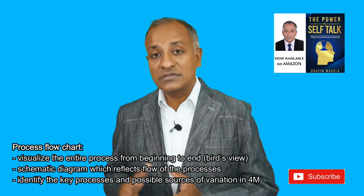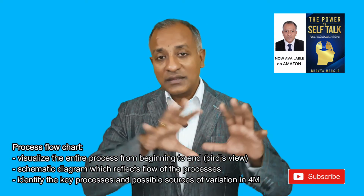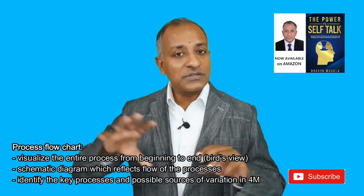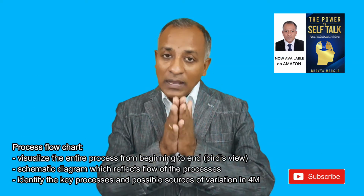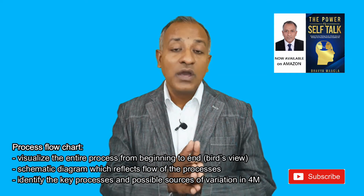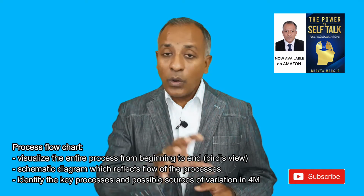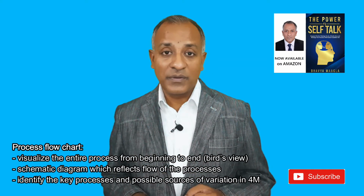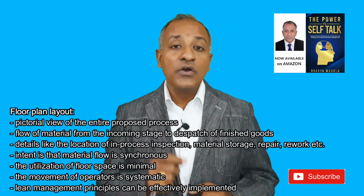Then process flow chart is another key output of this stage. Process flow chart talks about a complete picture of the entire process, that from incoming inspection to the dispatch, how the process flow will move, and that also helps in the PFMEA stage to identify what can be the possible variation in the 4M, man, machine, material, method. Once the process flow chart is prepared, it's very easy to identify and prepare another document, that is floor plan layout.